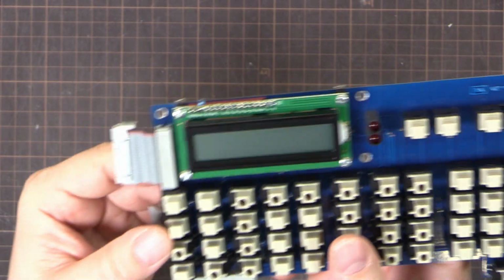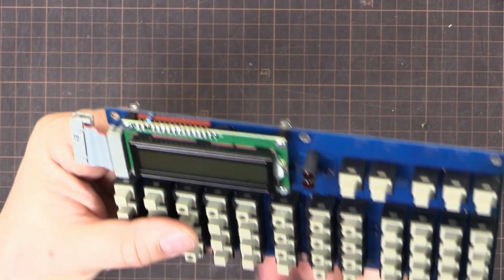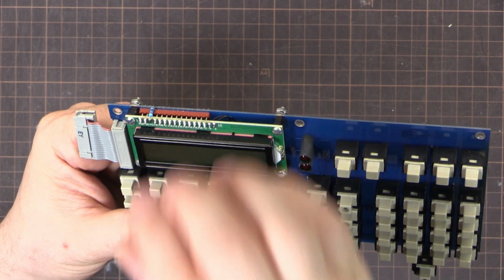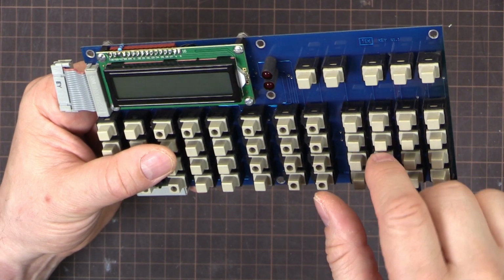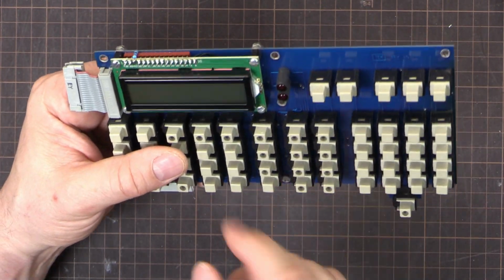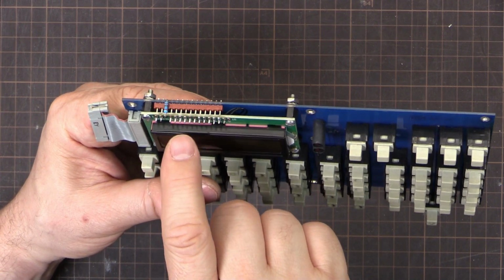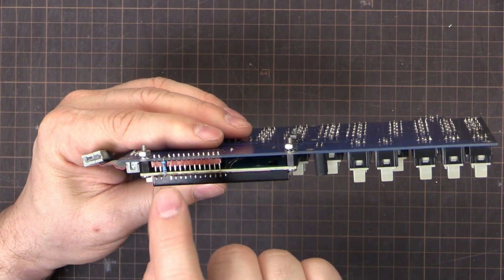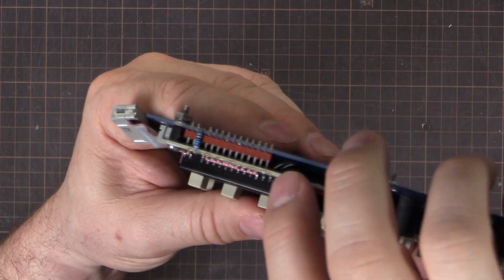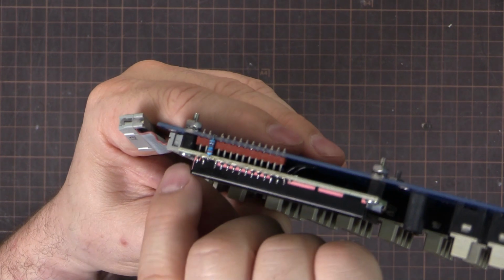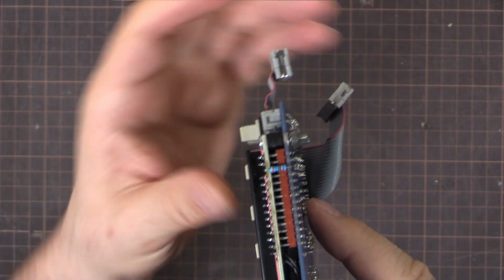And then the last one is to do with the contrast. It seems the contrast is a lot different on this. I found that when I put this in, it was really dark. It was all just black, and I had to change the settings all the way down to the lightest setting to see anything on the screen. So what I've done is pin 3 from the left is actually the contrast pin. I've pulled the pin out of the header there. I just desoldered both sides and used my needle nose pliers to pull the pin out. And I've put a resistor there, 3.6K resistor.